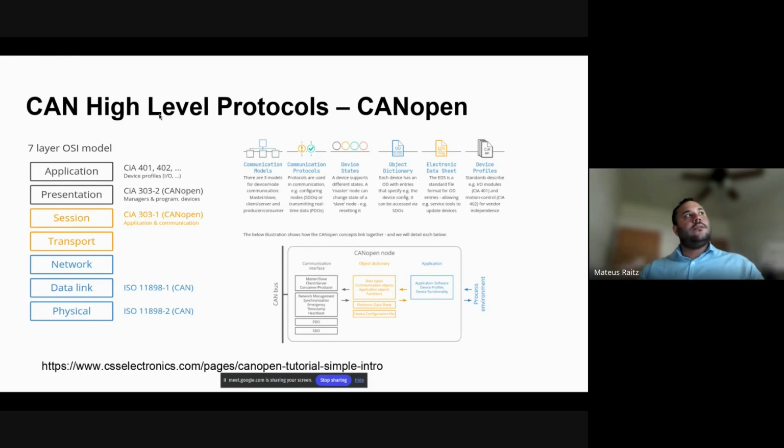So you can use different motor controllers from different vendors, or several motors, and if they are CiA 401 compliant, the interface will be the same. But you can also define your own dictionaries to communicate with the nodes.